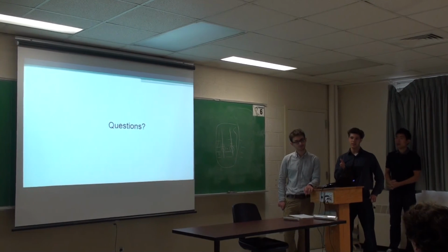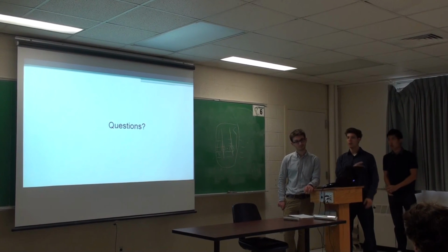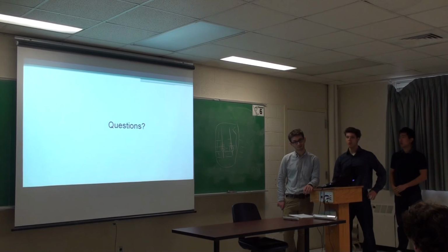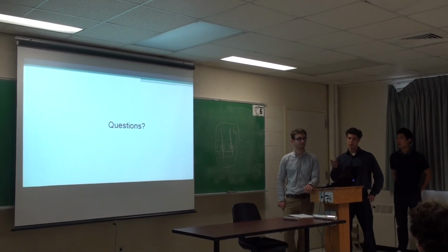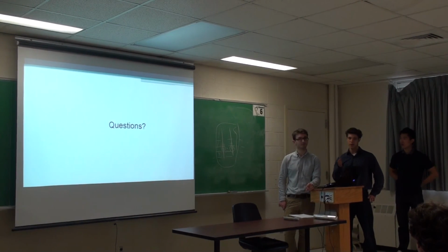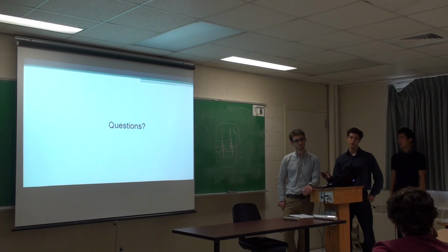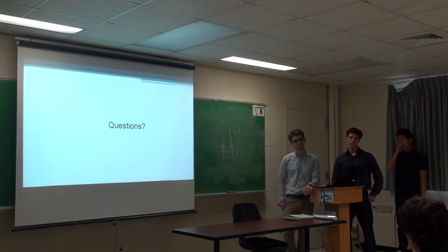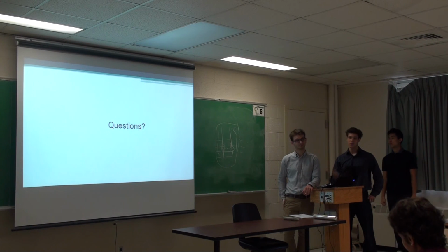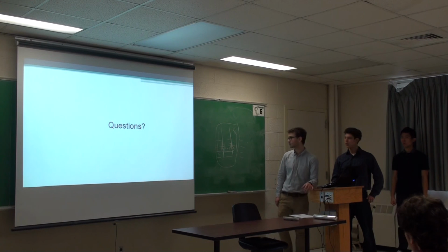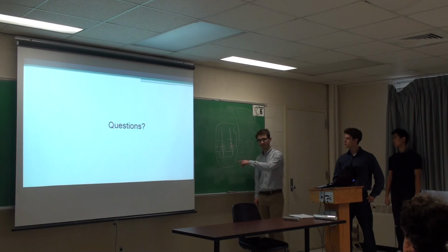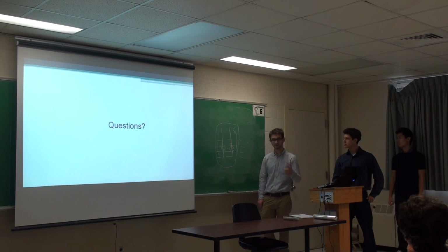What I think you're asking is, you know where the edge is in the image, but how do you quantify the position of the edge? Right. So we can detect which pixels are triggering where the sharp contrast between colors is, where the edge will be. Using that, the software can output data on where the position of the edge is in the image, and then we can just take the second edge minus the first edge and divide by 2. We wouldn't be able to tell you how many feet this is because we don't know where the position is going to be relative to the actual steel strip. They could put it anywhere.